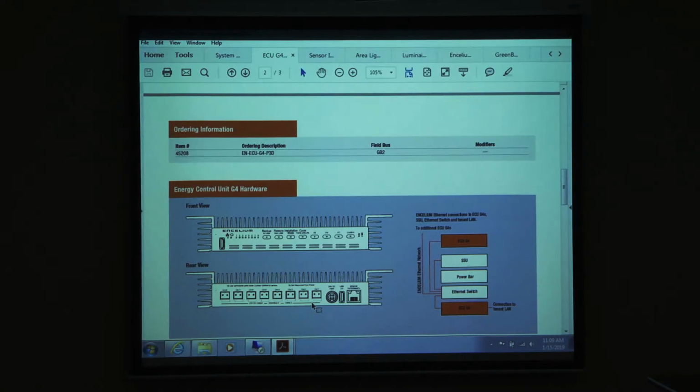One second here, I have a question for you. What happens when the ECU fails? The ECU is powering the whole channel, so when it fails, all the devices go normally closed. Once they go normally closed, it allows the voltage to run through the contact and energize the ballast or the driver, and the lights come straight on full. So the lights will be bright, and there are buttons on the wall, but you can't do anything with them because there's no control.